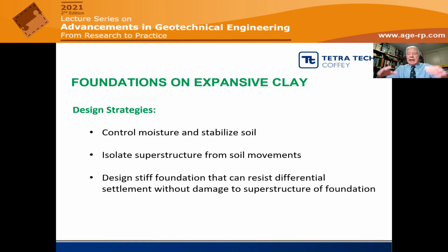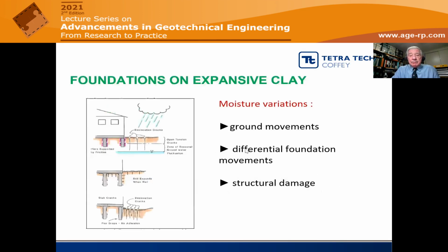If you get a drying out of the soil, then it tends to shrink. Now, you have certain strategies. You can try and control the moisture so that you isolate the soil from moisture changes. Well, you can try and stabilize it, or you can try and isolate the superstructure from soil movements, or you design a stiff foundation that can resist the differential settlements.